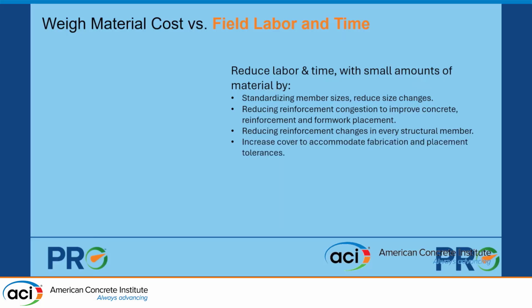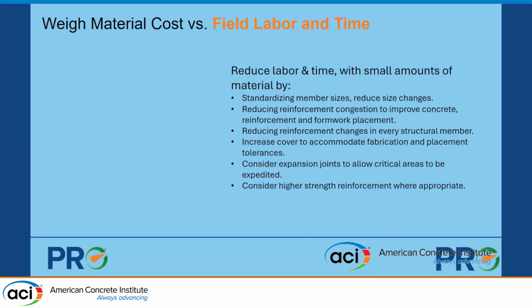Increase cover to accommodate fabrication and placement tolerances. Consider expansion joints to allow critical areas to be expedited. Consider higher strength reinforcement where appropriate.